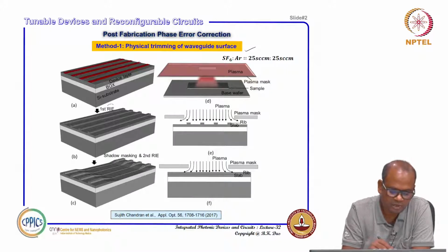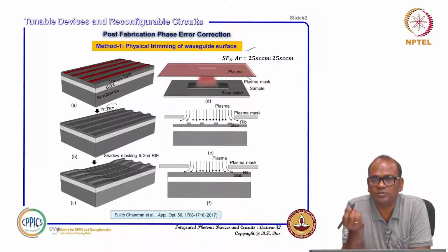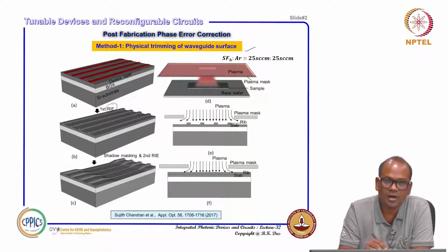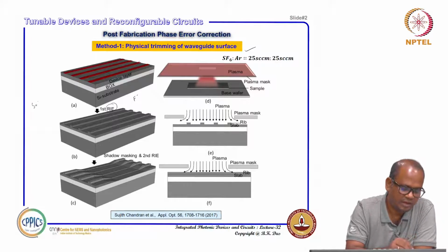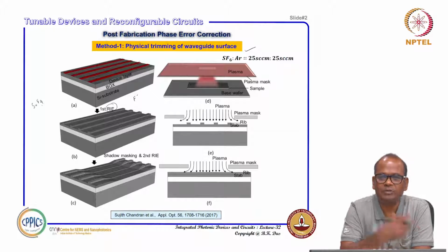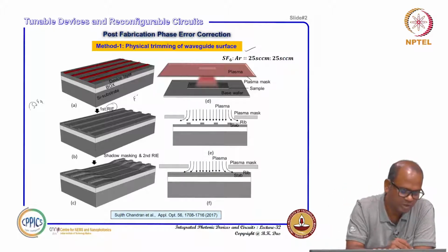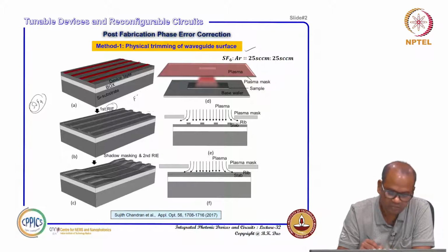In the rest of the region you can do reactive ion etching. Reactive gases are pumped into a chamber where your substrate is, and then triggered to create a plasma. The different ions in the plasma, specifically fluorine ions, interact with silicon and create SiF4, which is a volatile gas that can be pumped out. So silicon is consumed to create SiF4, and that is how you etch and define a set of waveguides.